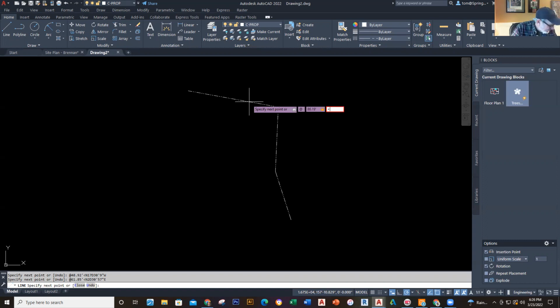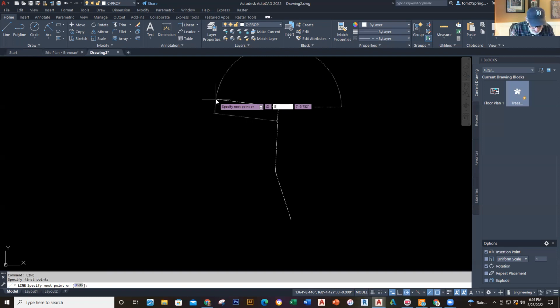Okay, let's see what I've got. Let me try that again. So we'll repeat line, and I'll click here, and I'm going to type in @ 86.19 feet less than N85D, then 36 minutes, 24 seconds.